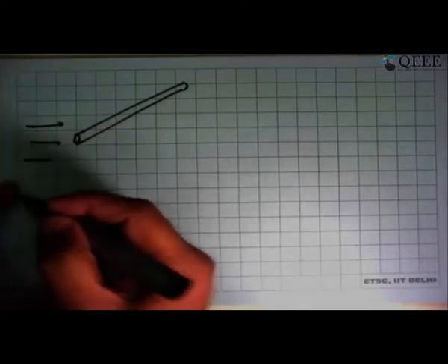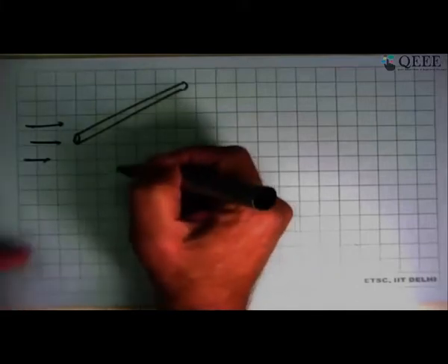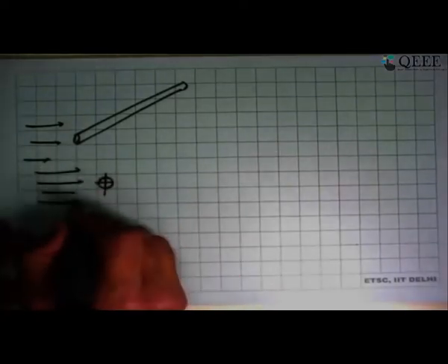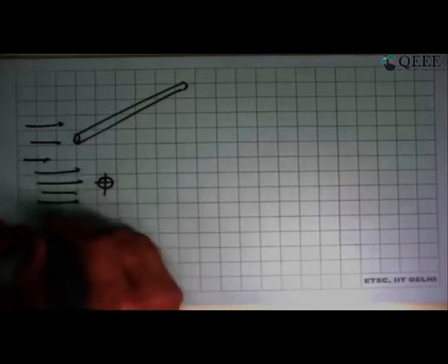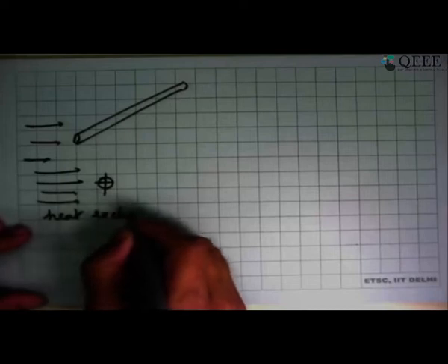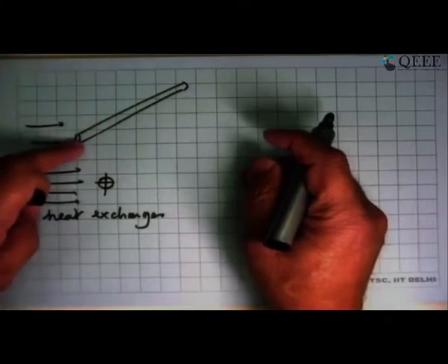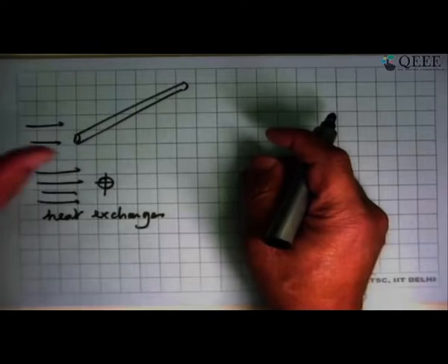One of the most common places where it will be used is when you have a tube with a fluid flowing on it. This is like a heat exchanger where there is a second fluid flowing through the tube, but one fluid is flowing across the tube. You have a circular tube there, and the fluid comes flowing over it. So a very common application is inside a heat exchanger, where the fluid is moving across the tubes. I need to know the outside heat transfer coefficient, and the inside heat transfer coefficient, and then I can get the overall heat transfer coefficient and design the equipment. So a tube in cross flow is a very important and very basic type of problem.